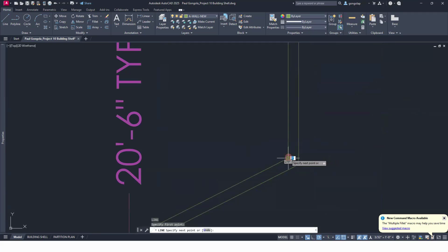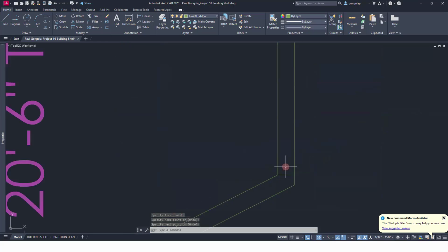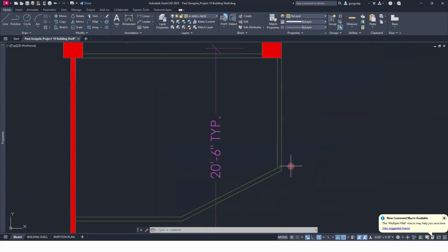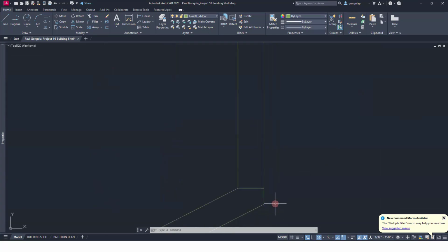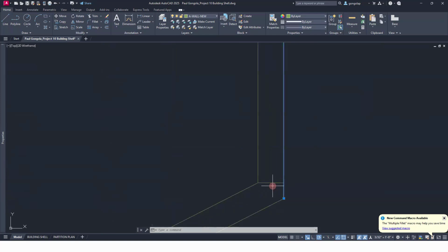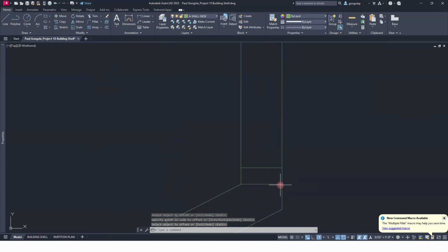So the line ends more or less here. And then I'm going to have a window frame. I'm going to have a door and then a window over here. I'm not going to draw it all. You know what? I'll do this much. So I need to break this. This little piece right here is part of my wall, and this is the edge of the wall. Then if I offset 2 inches here, that's my window frame. So I have to break this line into two parts. This part is on the glazing layer, and this part is on the walls layer or the partition layer.